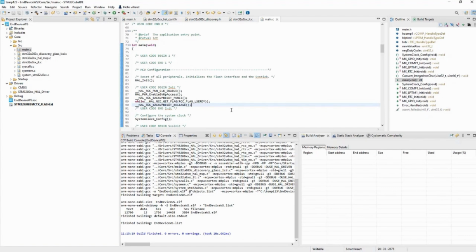So if you have a reset, or just the main VCC disappears but not the VBAT, you will keep the configuration of the backup domain and of the RTC. And we don't want that, because when we start from the reset here, we want to clean everything and be sure that the RTC is back to its virgin state.